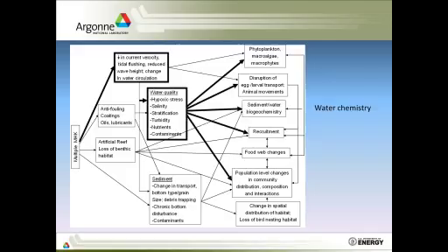Now, with some of these hydrologic changes, you could also see some changes in water quality. For example, if you have reduced tidal flushing, you could have potential for hypoxic stress within an estuary, or you could reduce river flow, which could create kind of a dead pool effect in a river. Also, you could reduce the penetration of salt water into an estuary.